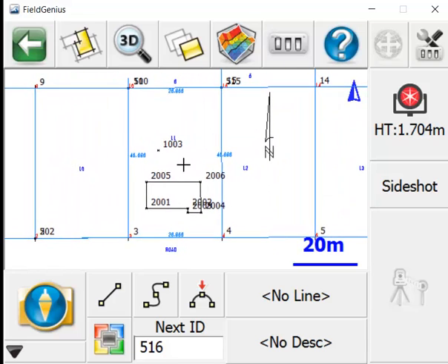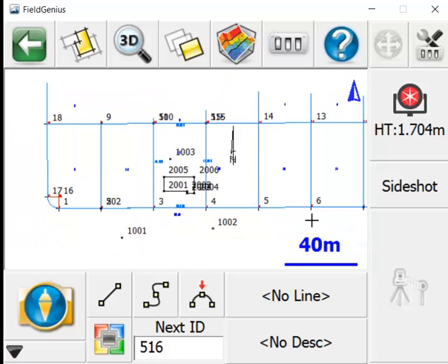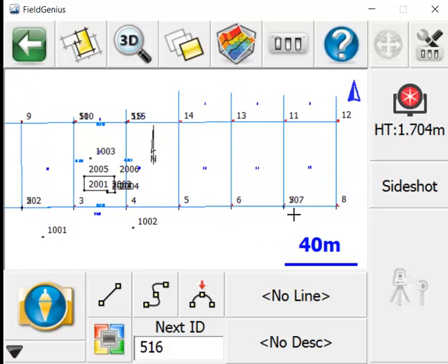And so what you'll notice here is that the house that we had tied in before is now oriented square to the lot. You'll notice how there's a point cluster here. There's less of a point cluster here because this is point 15 that had a poor fit. Another point cluster there, and over here at 7 as well. So at this point you can continue working.